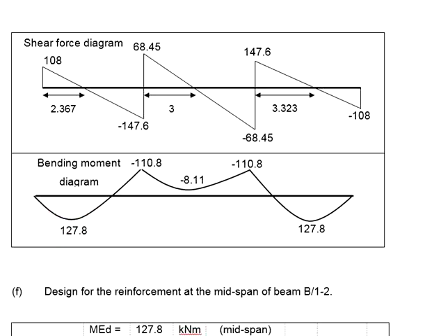However, if you are dealing with the support here, you have negative moment. Now your tension steel bar will be at the top of the beam, whereas the compression steel bar will be your bottom bar. You will need to be careful on this.